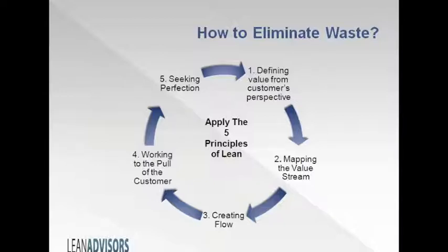Right? And what happens if you don't do the map, the value stream mapping, you fail to visually see where your opportunities to eliminate waste are. And the reason you want to do a value stream map is because you want to get everybody to release what is in their mind back onto paper so you can see it. And that's when you'll get those, oh yeah, aha moments. Those are the things you do. And that makes it all the more meaningful and also takes the subjectiveness out of the process and brings in some objectiveness because you're going after now areas of process defects as opposed to saying, I think Tony's messing up over there. Now you know all the steps that have to go on.